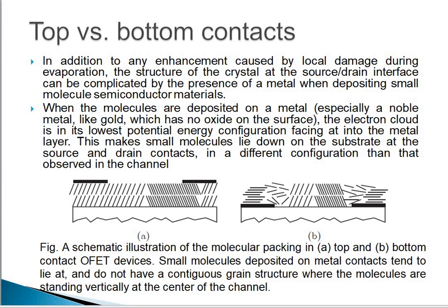A schematic representation of molecular packing in top and bottom contact OFET devices is shown in the figure. Small molecules deposited on the metal contact tend to lie flat and do not have a contiguous grain structure, whereas the molecules are standing vertically at the center of the channel between the source and the drain contact.